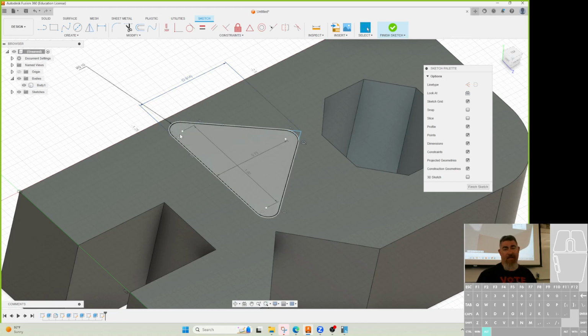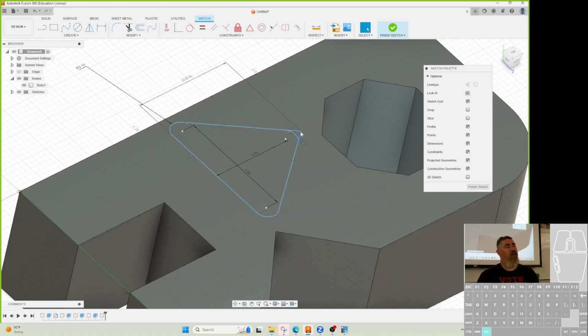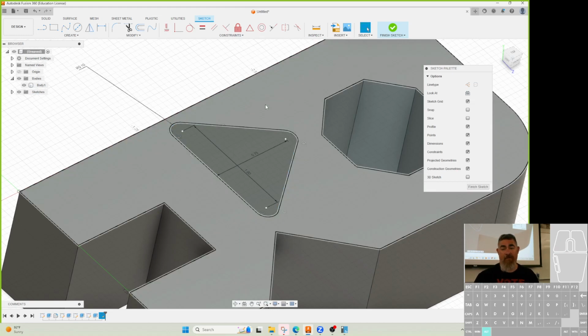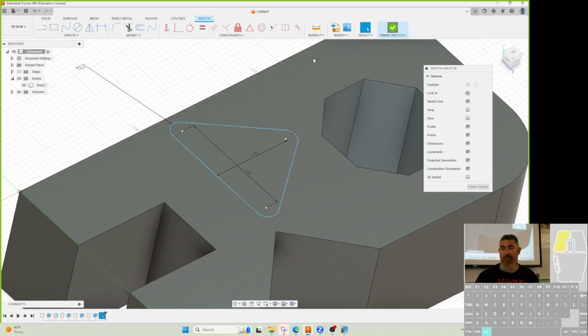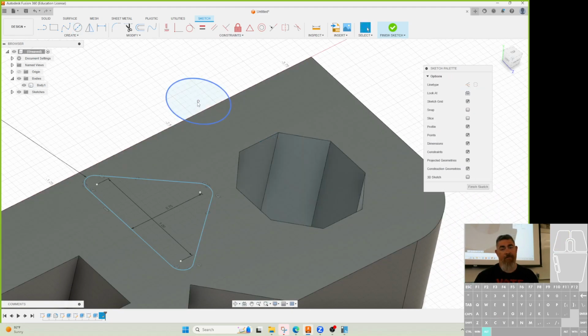I don't have to know it because I can dimension to the center point. Okay? And that's why in this case I wouldn't draw the point. Because the center is what I care about, draw the center. Alright, so that's the only time I would actually sketch the centers. Or same thing if I had, I need to do a center cut off of here.